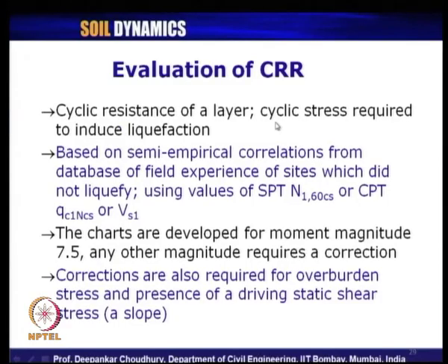So, that is why Seed and Idriss, when in 1971 they proposed the equation for factor of safety, gave the equation as CSR at 7.5 by CSR, meaning they have used both CSR. One is required to induce liquefaction at an earthquake moment magnitude of 7.5, relative to how much cyclic stress ratio is actually getting developed for a particular earthquake.